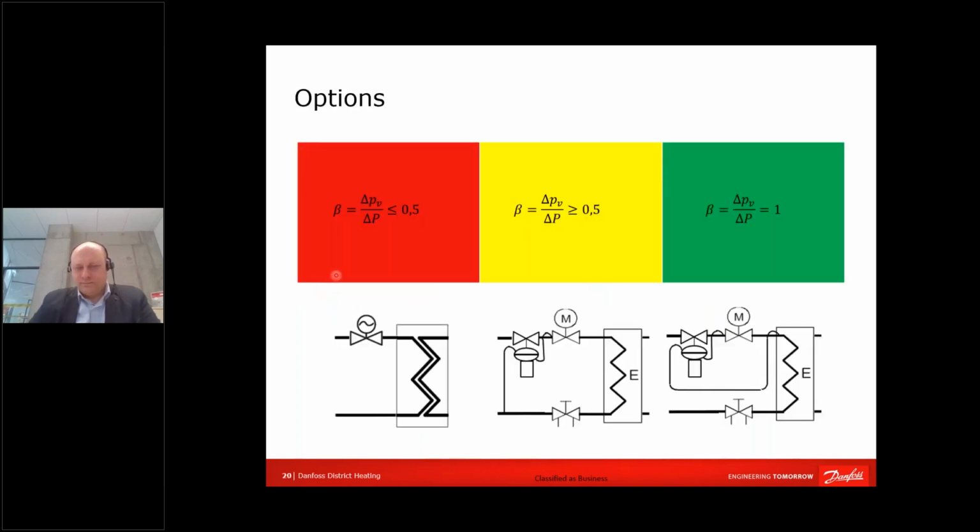I just drew the scenarios which are happening. The red one, where we have no differential pressure control, probably will be the worst one. The yellow one, like a street light, will probably contain some components, which is sometimes okay. And the best scenario is when we do have differential pressure controlled across the valve. Of course, that is leading to a single pressure controller.